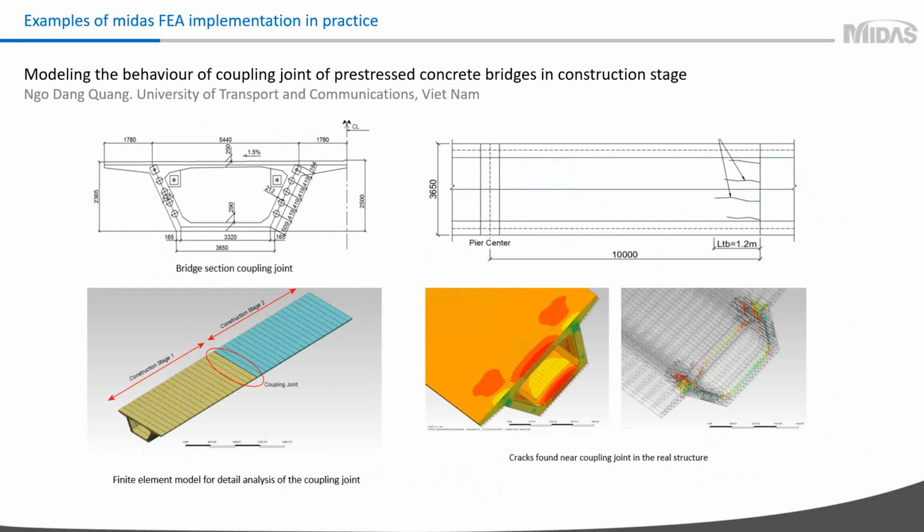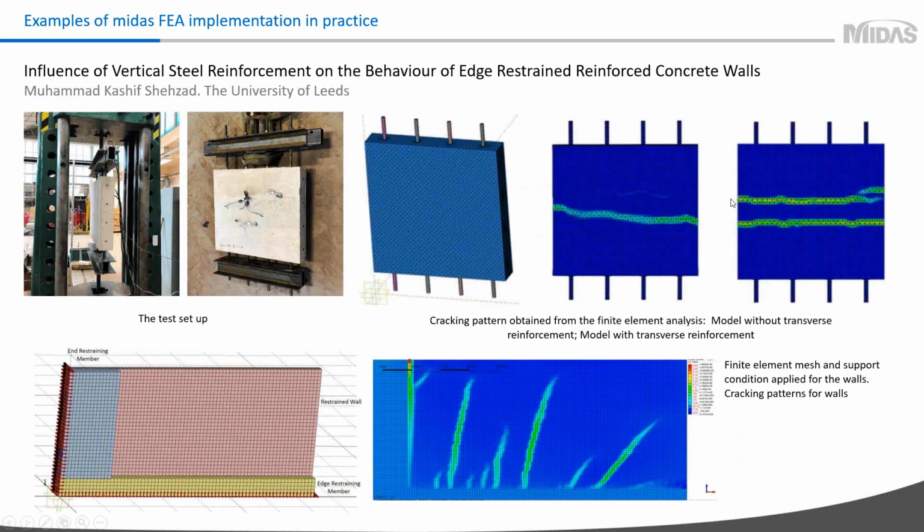He used the Thorenfeldt softening for compression, and multilinear softening for tension. The user in this model considered many actions like creep, shrinkage, heat of hydration, and prestressing. This combination of all of these actions allowed him to predict the longitudinal cracks at joints.